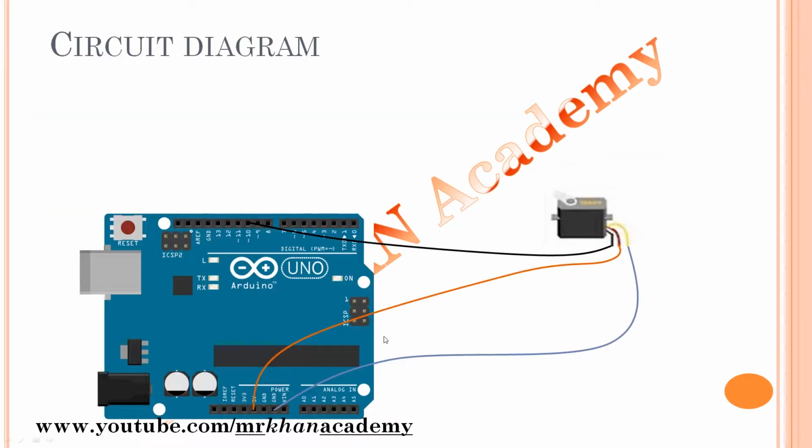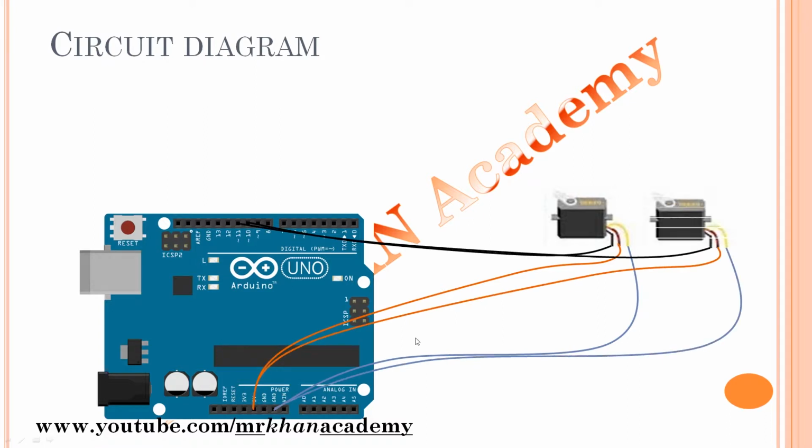In the second project, you can see the connection is similar. The first motor is connected the same way: the first pin to digital pin number 10, the second to the 5 volt supply, and the last to the ground. But as I am using two servo motors, the second one needs to be connected separately. The first servo motor uses digital pin number 10, and the second motor uses digital pin number 11. You can change the pin anywhere, it is not fixed.